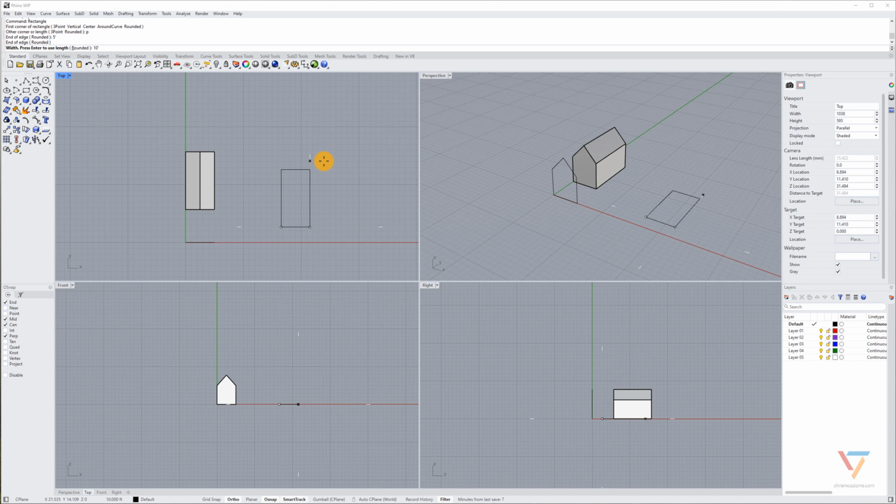And again, I'm using the apostrophe to represent feet. A quotation mark would represent inches, and you can do both at the same time. 10 foot 6 inches would be allowed, but I'll say 10 feet this way, and then I'll use another line here just to show that roof. Right? So instead of relying on the three-dimensional object, I can draw a two-dimensional drawing here that explains what that is.